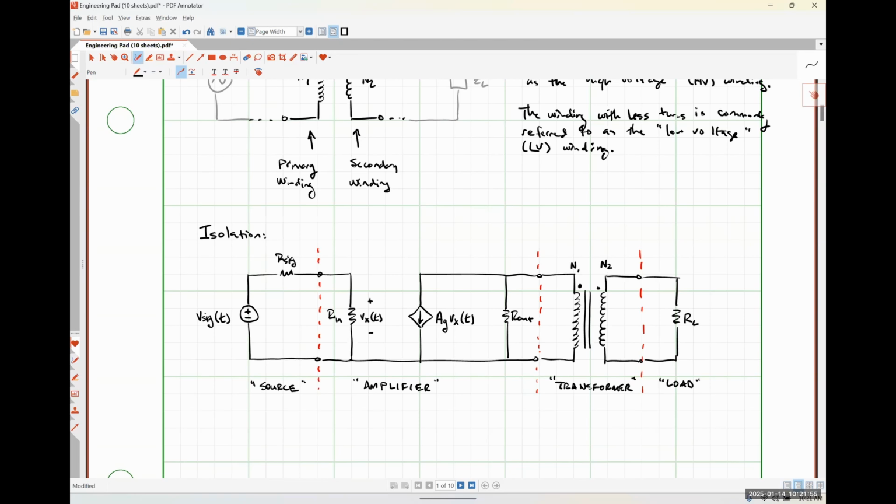So 4 ohms, 8 ohms, 16 ohms are typical values, right? So pretty darn low, right? So depending on, like if you have a single, let's say a 12-inch speaker or something like that, its impedance is probably 16 ohms. You have 2 speakers in a cabinet, the overall impedance is probably 8 ohms because it's those 2 16 ohm speakers connected in parallel. If you have a 4x12 cabinet, it might be 4 ohms, it might be 8 ohms, it might be 16 ohms. It just depends on how it's wired. But typically speaking, the impedance of a speaker is very, very small. Single digit to tens of ohms kind of thing.